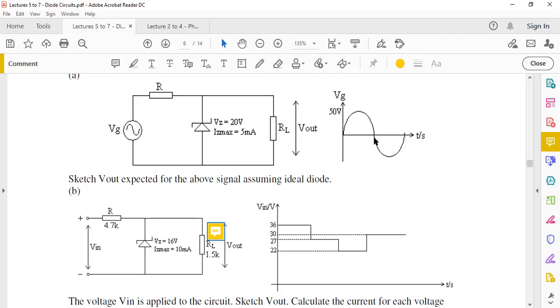Yeah, so it means as your input voltage is changing, of course, when your sinusoidal waveform is in the negative mode here, you simply have a current that's going to flow here, and it's going to have a short circuit of this one. So it means you're short circuiting RL. You just have this path, which is going to be relevant. So basically, in the reverse mode, you would simply measure 0 here. So I hope it's clear.